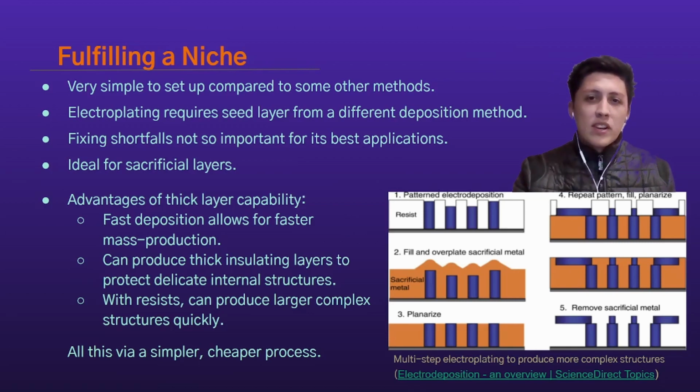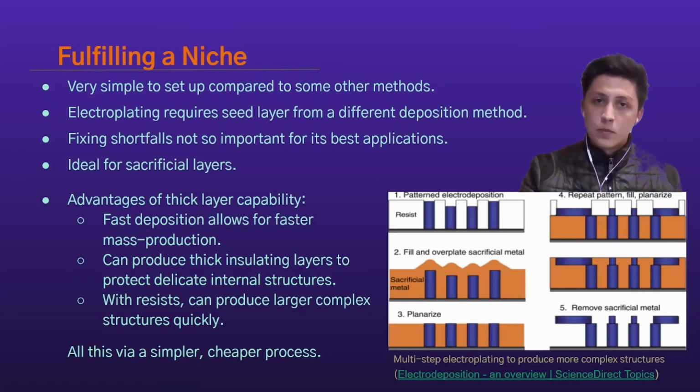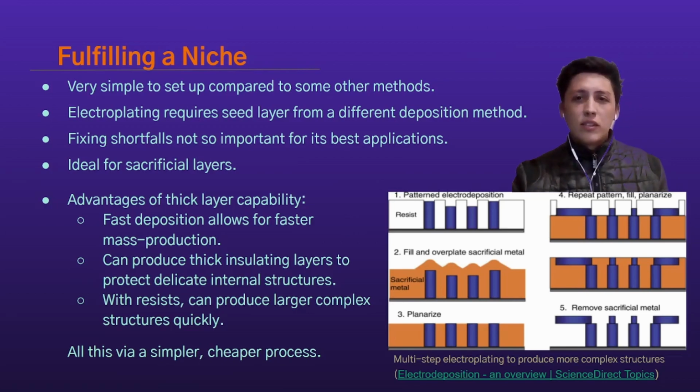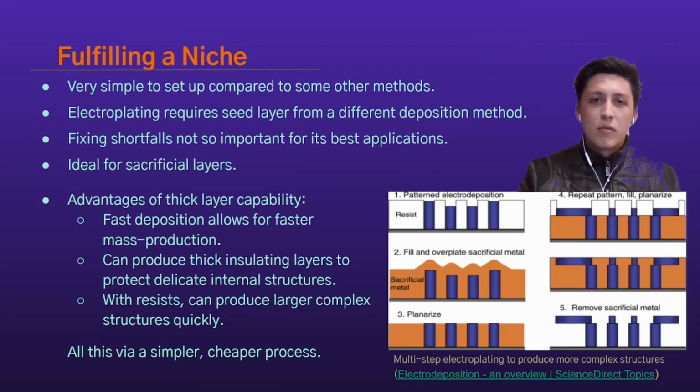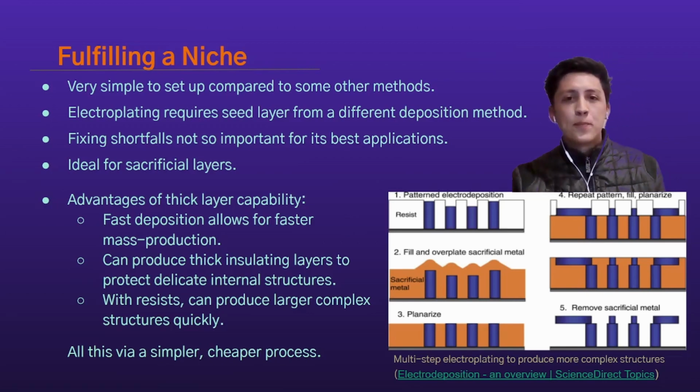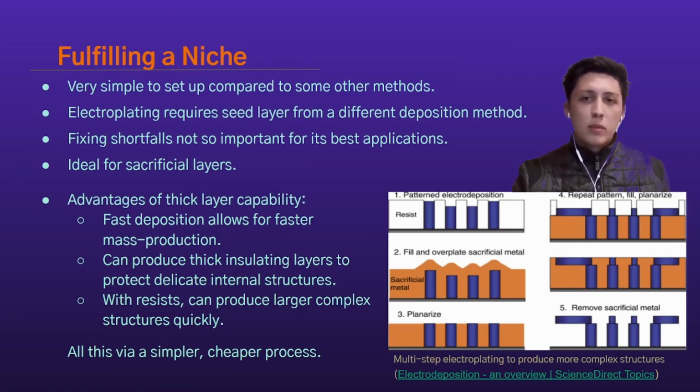The requirement for a conductive base upon which the electrodeposition grows also means that electroplating can be applied locally through calculated use of mask patterns. Unlike many other deposition techniques, which apply particles to form layers over an entire substrate or wafer area, electroplating will only proceed where the seed layer exists. Resist can be used to ensure electroplating only forms metals where desired, and also allows for the production of intricate microscale shapes in some cases.